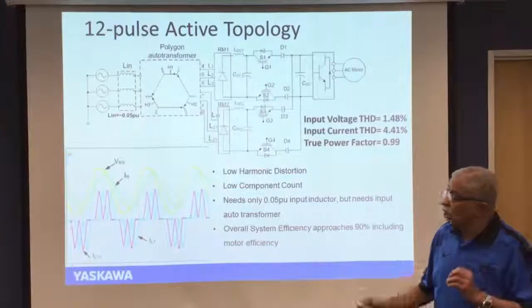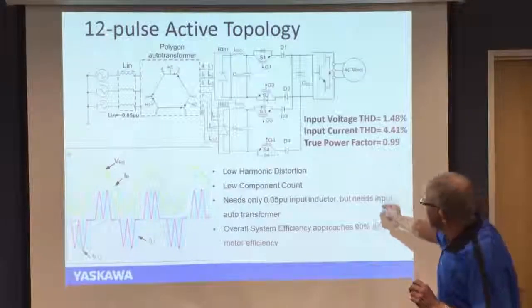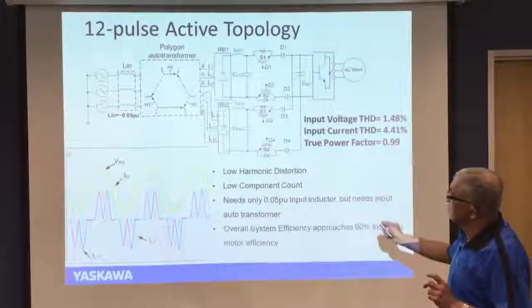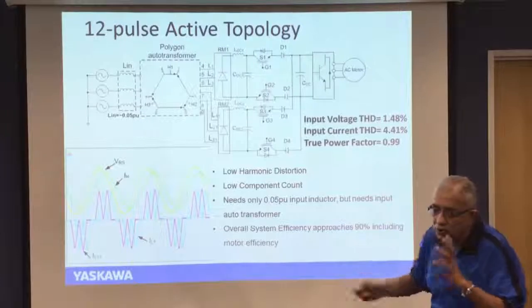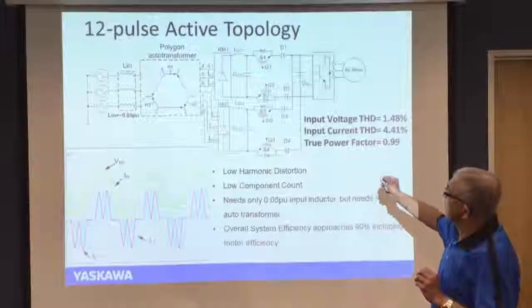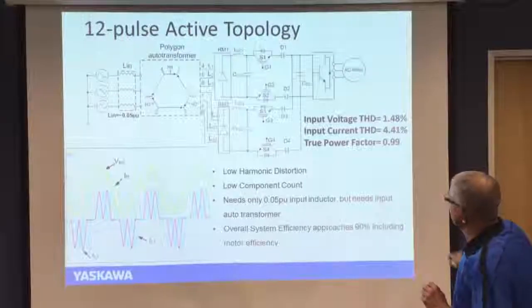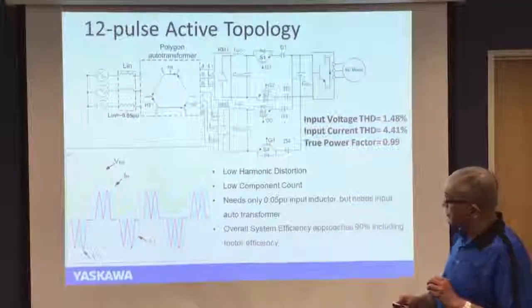In fact, we could have a DC bus and we could have multiple drives on this DC bus, and we could have one big or one cost-effective AC to DC active rectifier, and we could have our DC transmission with many loads on this, then it would probably make more sense.